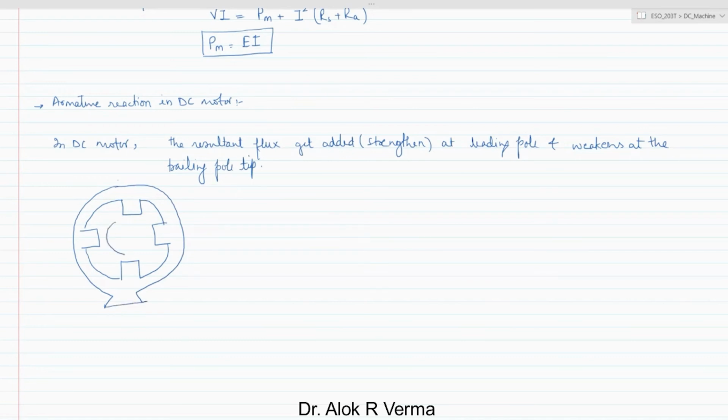And you have a rotor in the center. So this is north, this is south, or if you're rotating this way, you can discuss in north or south. This is the rotor. So you have the interpoles which are connected here. These are known as the interpoles, to neutralize the effect of armature reaction.